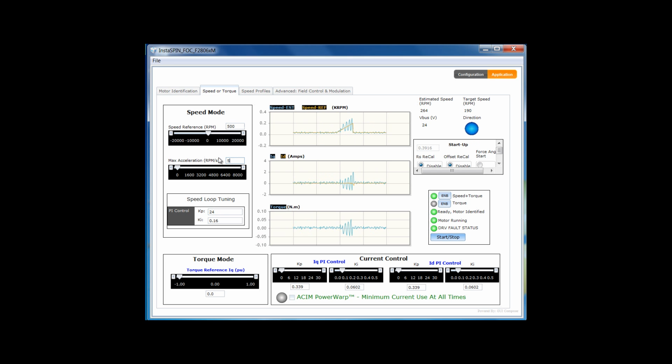I'm going to go ahead and increase. This motor can handle much faster acceleration. And you can see I'm already getting some instability because my gains at 0 speed are actually too stiff once I'm moving. So I'm going to go back closer to the original value. Remember my original value was 8, so I'm here about 50% higher, and you can see that I'm keeping about 500 RPMs here.